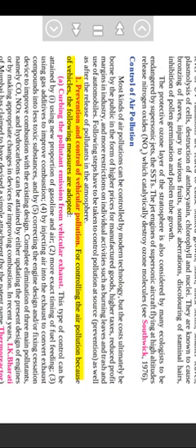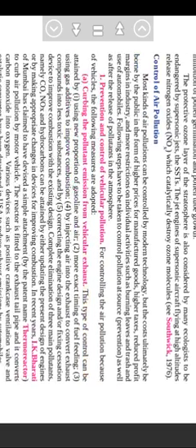For controlling air pollution because of vehicles, the following measures are adopted. A. Curbing the pollutant emission from vehicular exhaust. This type of control can be attained by 1. Using a new proportion of gasoline and air. 2. More exact timing of fuel feeding. 3. Using gas additives to improve combustion. 4. By injecting air into the exhaust to convert exhaust compounds into less toxic substances. And by 5. Correcting the engine design and/or fixing a device to improve combustion with the existing design.